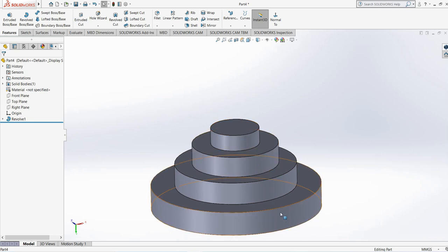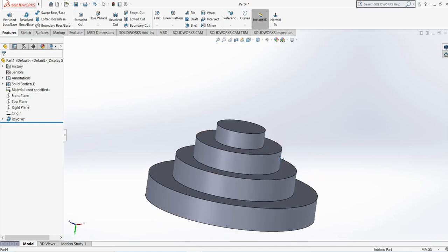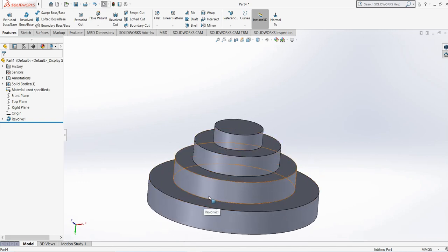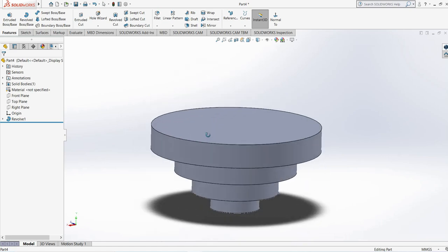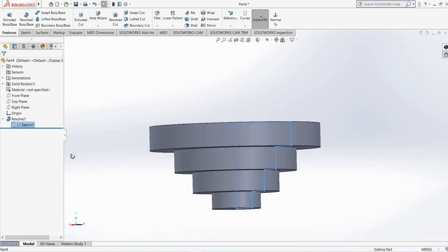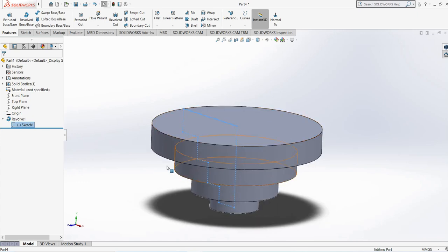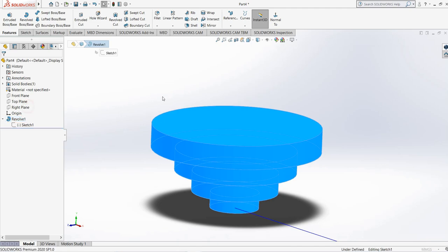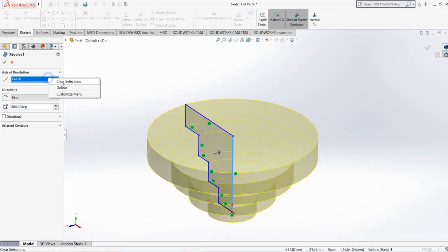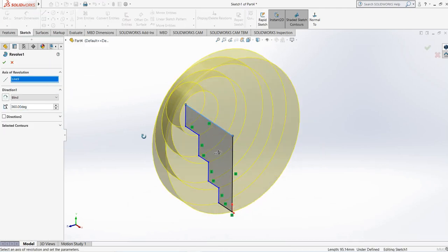So if we use the extrusion tool, we have to do this extrusion, this extrusion, this extrusion, or this extrusion, at least 4 or 5 sketches, or we can use the contour selection tool to draw this, but we have to use 4 extrusions to make it. But in the revolve tool, we only draw this half structure like this, and we will revolve it around this. Or we can also use the revolve axis like this one also. So it will look like this,